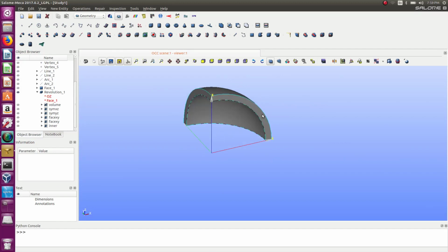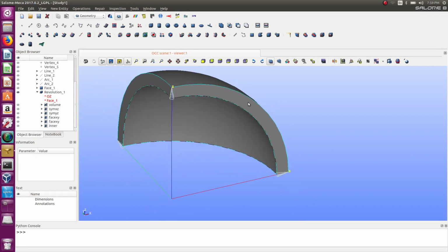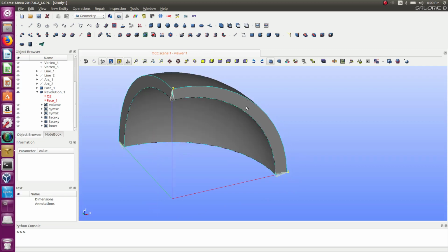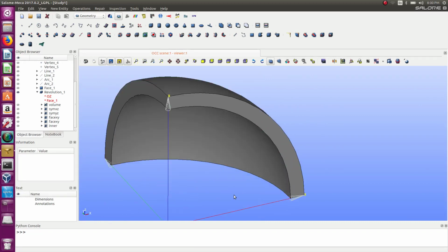Okay, now something more maybe that I will need is if I want to create my stress linearization in this area of my model, well, I will need to extract the position of this. So the best is probably to create a segment here in the geometry, and I will use this segment later on when I associate all of that to create my cutting line. So let's do that.